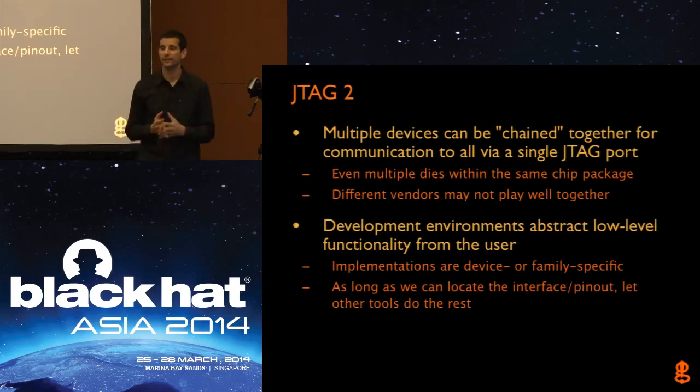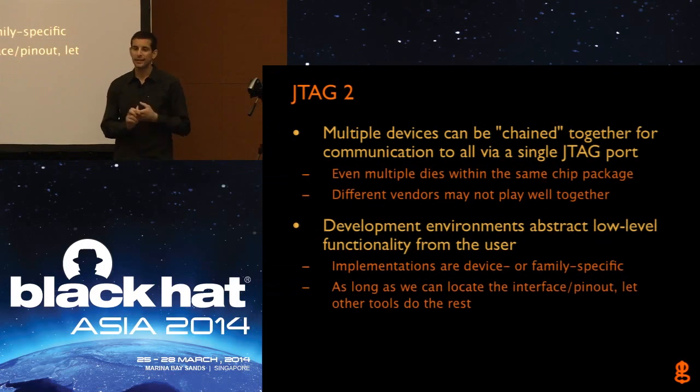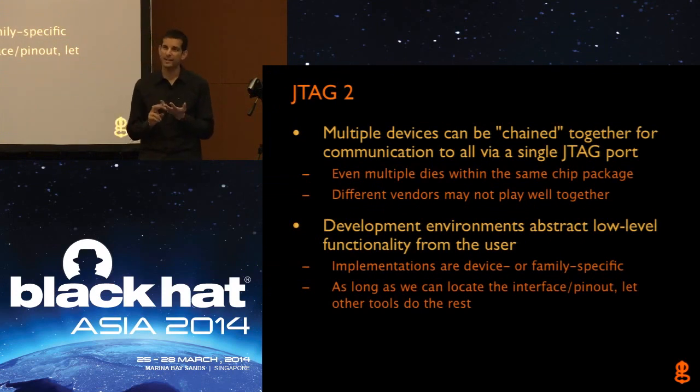As for the vendor-specific interfaces that are out there, Microchip has their in-circuit serial programming interface. Texas Instruments has their SPI-by-wire interface. Atmel has their ISP interface. Every vendor has their own programming and debug interface that they'll use if they don't use JTAG. But JTAG is just way more universal.